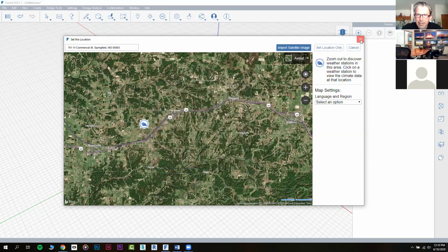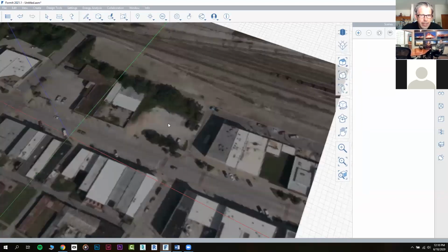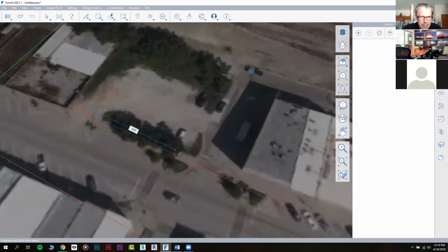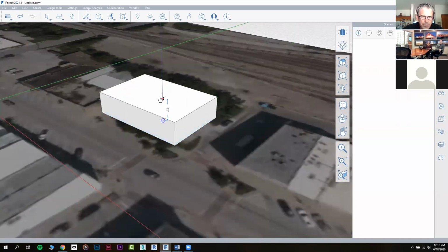So all of that said, let's cancel this and go back into creating a massing model. Again, I'm just going to use the sketching tools. I'm going to be drawing on axis with Commercial Street, so I should be looking for the purple axis for perpendicular. Then I'm going to use an inference snap to make sure I'm building a rectangle, and then I'm going to pull that up.